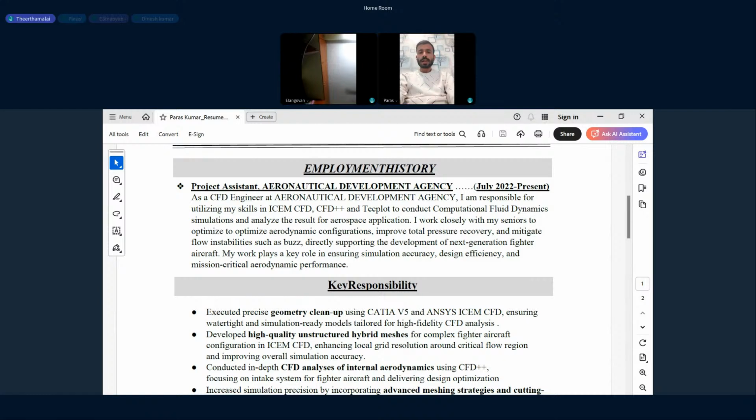Sir, pulses also we can go. Pulses on the intake, like rapid fluctuation of the total pressure. That is instability. If instability is there, your distortion coefficient itself will indicate. Okay, sir. Those things, instability and other things, buzzing, instability and surging, all those things will be taken care. All the instabilities also will reflect in terms of distortion coefficient. Okay.